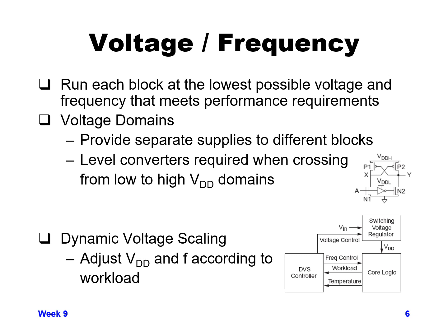Now, two of the problems that you have due to having multi-voltage domains and multi-frequency domains, one is for voltage domains, if you need to send signals between two different domains that are at different voltage, you actually have problems with a lower voltage signal trying to drive into a higher voltage domain in particular. And so you need level converters or level shifters in order to get the voltage up to the full value of the receiving domain when you're coming from a domain that's at a lower voltage.